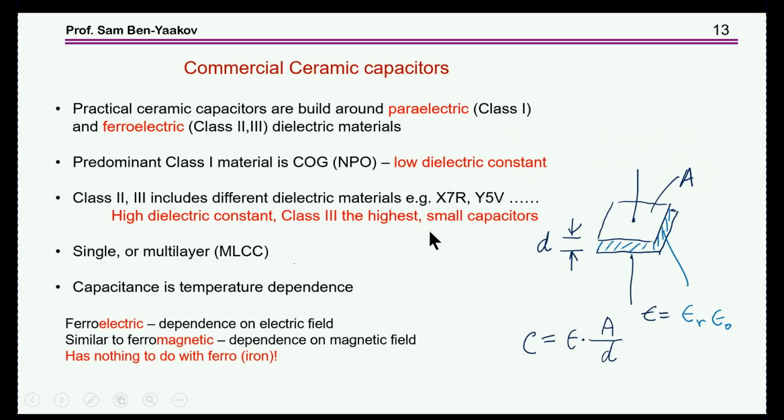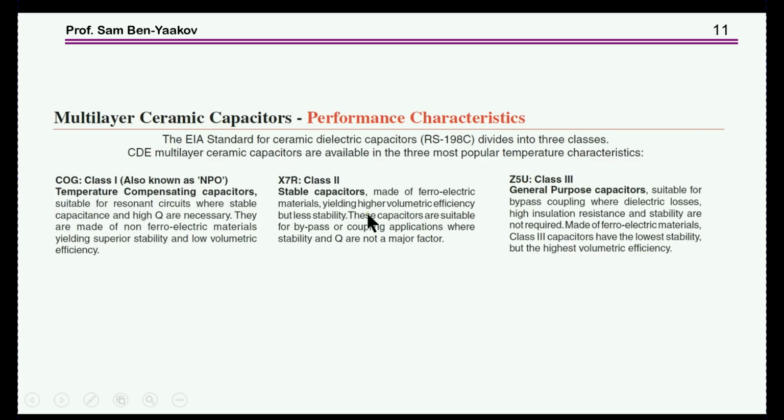Especially for the paraelectric, no question, this is a very good capacitor and very stable. So to wrap it up, this part here, we are talking about paraelectric and ferroelectric. NPO is the paraelectric one; class 2 and 3 are the ones that I've mentioned. And I didn't mention it earlier, let me just go back. I forgot to mention that